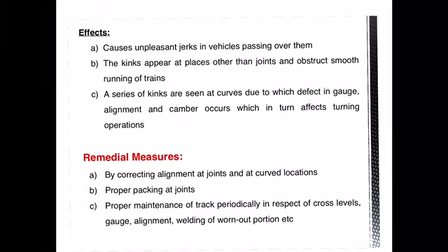And the third effect is a series of kinks seen at the curves, due to which defects in gauge can occur, alignment can be disturbed and the cambers can also be defective here. So with this effect, the turning operation of the train will be difficult for you.